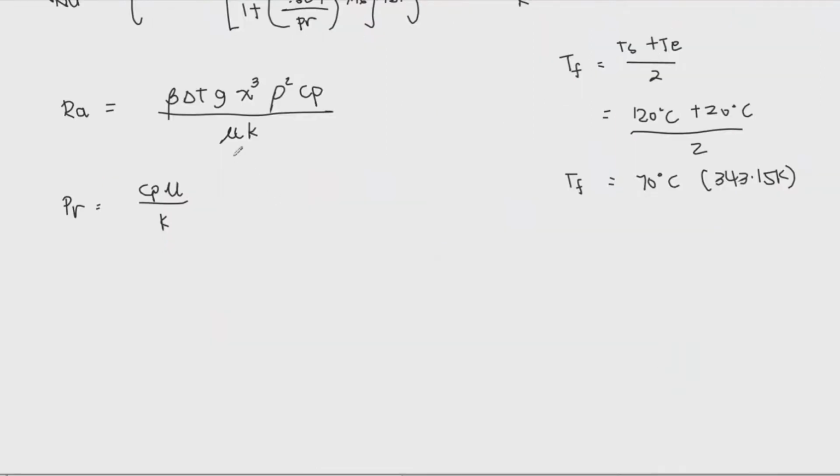Upon doing that, let me just write all the data I have pre-interpolated. At 343.15, which is at 0.1 megapascal, the value for the density is 1.0625, in kilograms per cubic meter. I also have the specific heat capacity, that is 1010.2043, and the unit is joule per kilogram Kelvin.